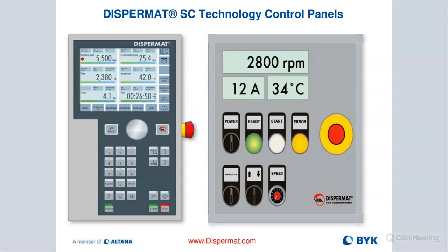The device also comes with safety features, a container clamping system. You can see we have two buttons right here. They allow you to set a threshold for the lower limit as well as the upper limit inside of your container. So you would preset that before you start dispersing or milling to ensure that you can operate within those two set points. If somebody were to inadvertently push the up button and it would pass the threshold that you set, the machine would automatically power down or stop at that reference point so that there would be no way somebody gets injured with this spinning disc outside of the container.